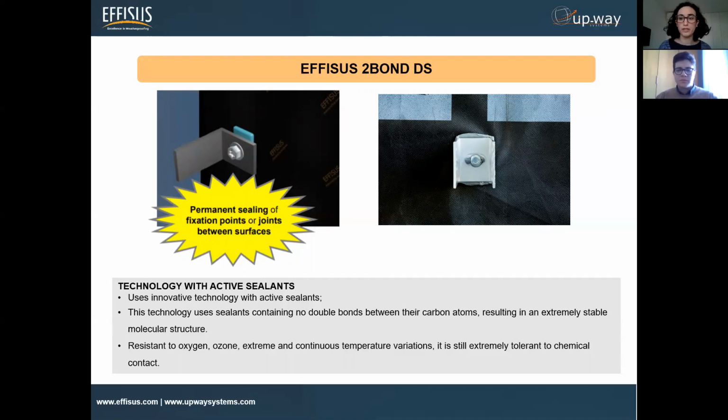So we have two checks, or we guarantee two types of sealant. First of all, with the adhesive itself, only applying a bit of pressure, and then with the elasticity, with the elongation. This kind of material has a very huge elongation of 500%. So we can say it embraces the screws perfectly.